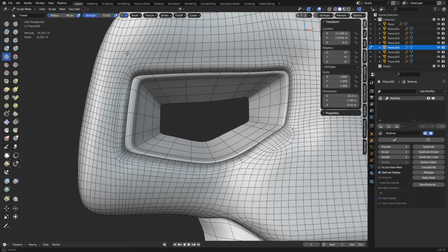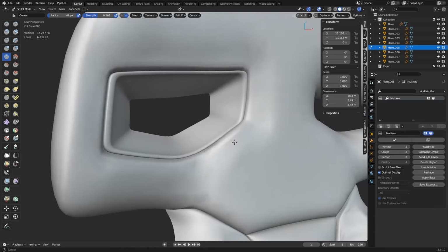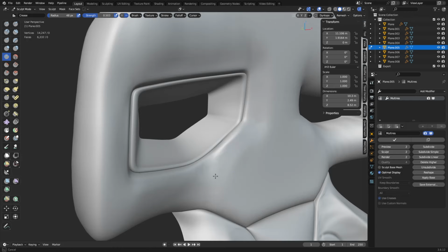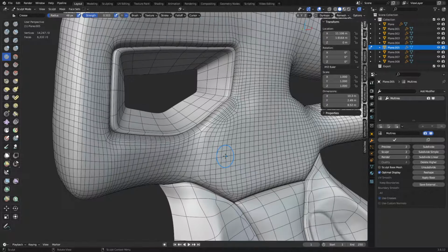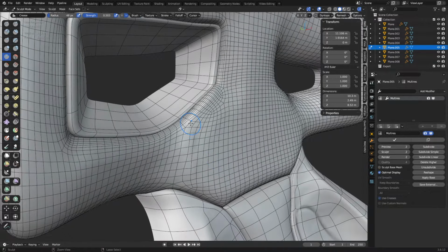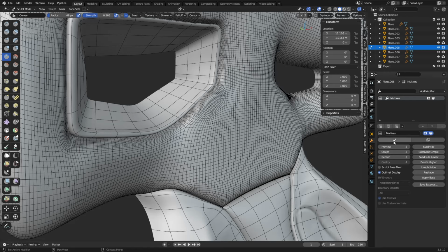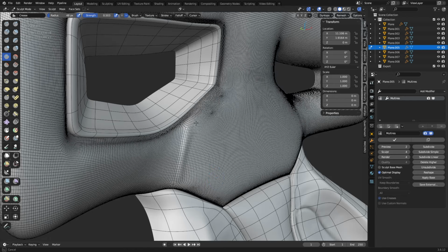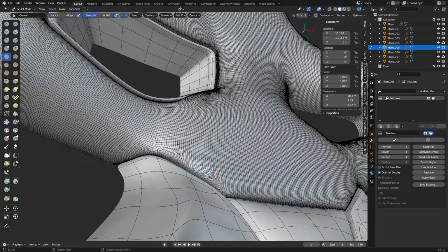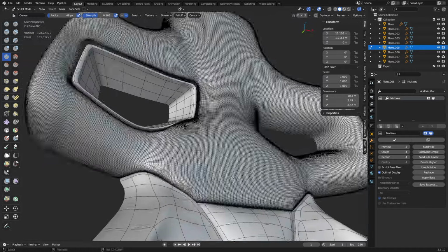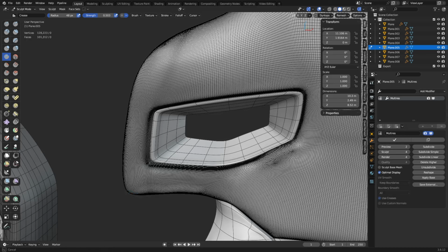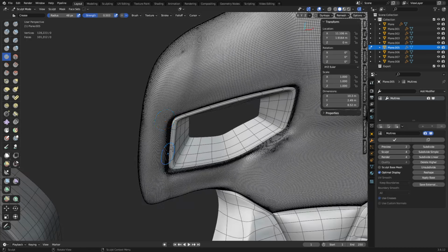All right. So you can see we have control over this area now though, which is nice. So if we need to sculpt in this area in particular, you see we don't have much resolution here. And it's a little bit messy. Subdivide more. Subdivide more. You can take these up pretty high too. They don't have to be low res. You see those poles now starting to have an influence here? That's why you want to avoid those, make better, cleaner topology than I just did, but it certainly is doable.